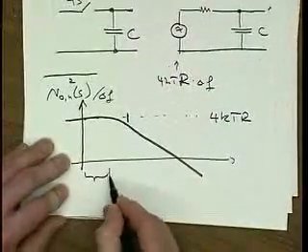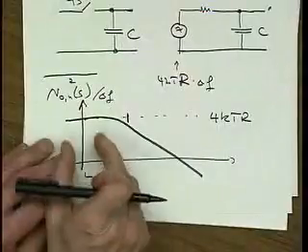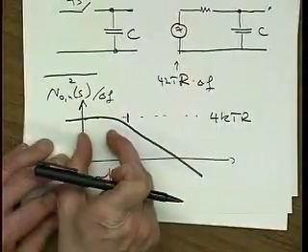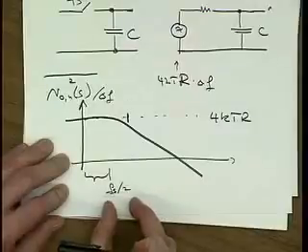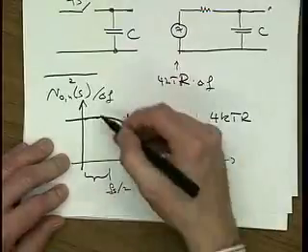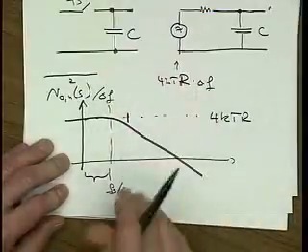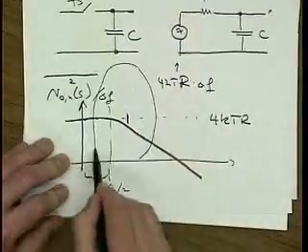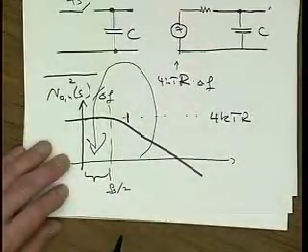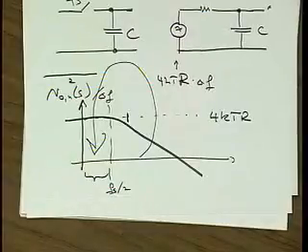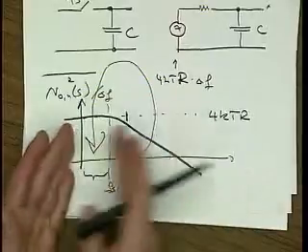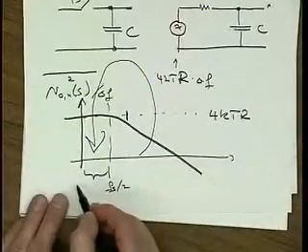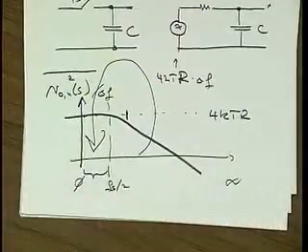So up to a frequency of Fs over 2, we really keep everything the way it is. And then everything that is beyond, in some contorted flipping way, is just falling into here. So what's the total power of the noise coming out of these things once we open the switch? Well, it's just the entire noise power integrated from 0 to infinity.